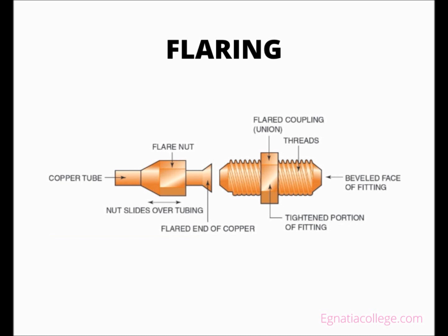Soft copper is used to make a flared pipe end that is mated with a compatible threaded flare fitting and flare nut to complete a connection. A flare nut, which is typically sold separately from the fitting, secures the pipe to the fitting. A threaded flare connection does not require pipe dope or Teflon tape and is considered a ground joint because it is a metal-to-metal connection.